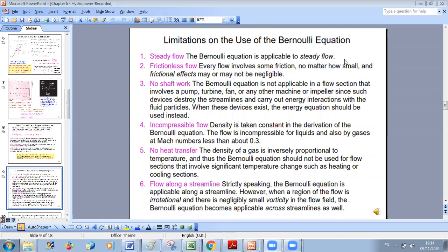I should be close to the turbulent zone, but not to have high turbulence, because high turbulence will destroy my streamlines. Okay, so if you want, Bernoulli is just applicable at the limit. So I have a high Reynolds number, but still not disorder and no losses due to turbulence effects.